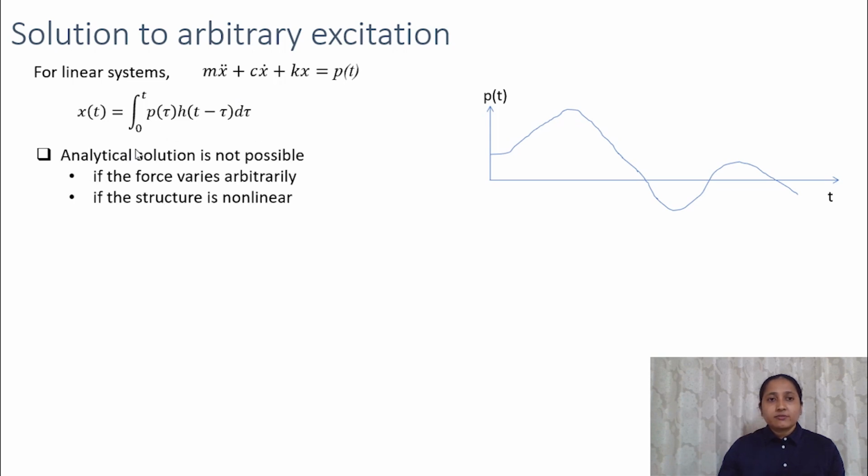But if the force is varying arbitrarily like this, for example, we cannot solve this integral analytically. Also, if the structure is non-linear, then this term will also be non-linear. In that case also, solving this integral analytically will be impossible. So we have to solve this integral numerically.